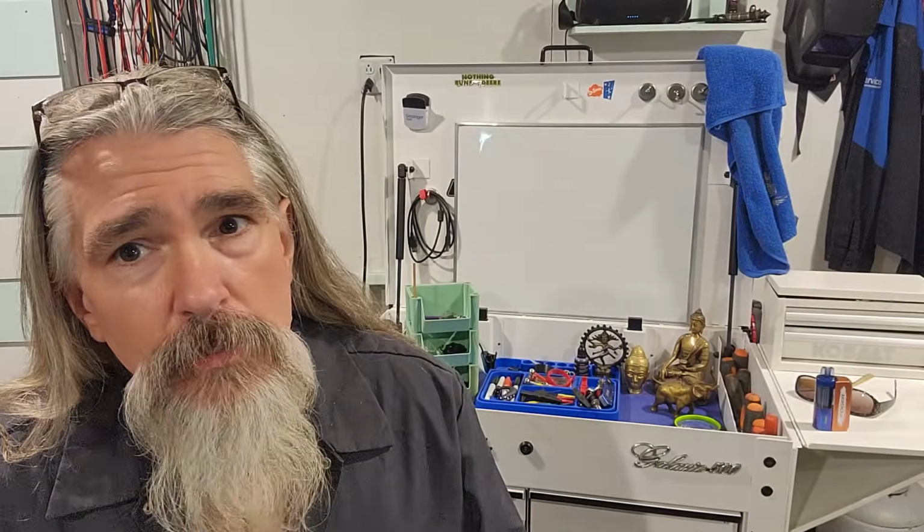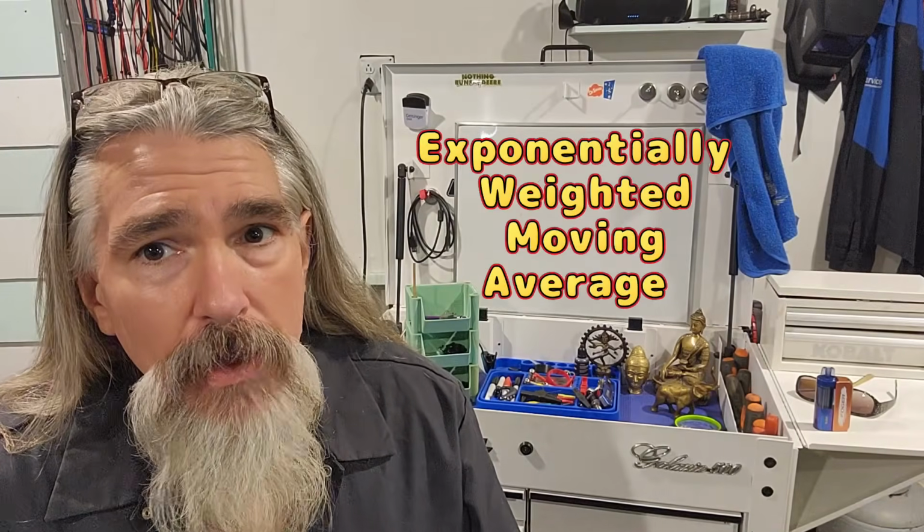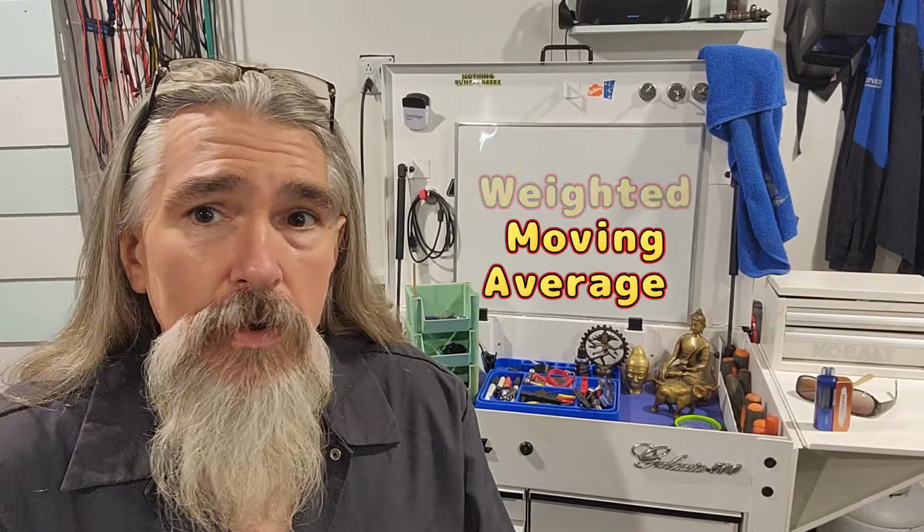Right above it, there's something called exponentially weighted moving average, EWMA for short. Now, you're going to see that on any scan tool. It's not under the factory. It's under mode 6 under global. You could see your misfires. But now, if you see a number under that EWMA, you know the computer was looking there. It picked up something under that circuit last time.